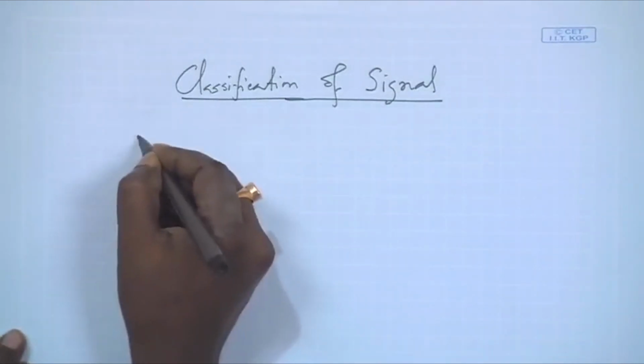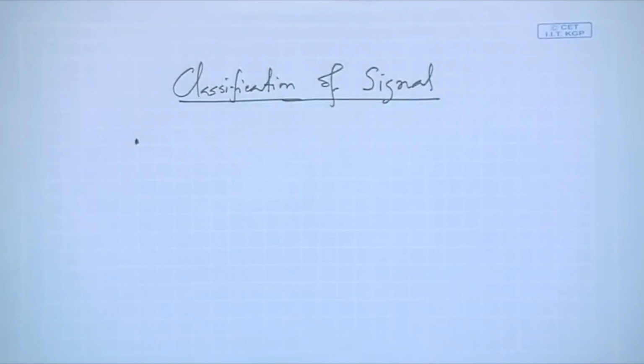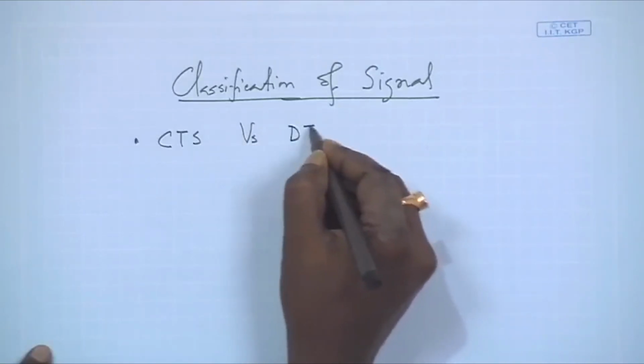One way to classify is, see, any signal we were describing had an independent variable which is time. For our case, it might be other things also, but at least here it is time. Whenever we classify the signal with respect to time, there are two things. One is that the signal is defined in discrete time, and the other is that the signal is defined always, that is continuous time. So I can have a continuous time signal versus a discrete time signal.